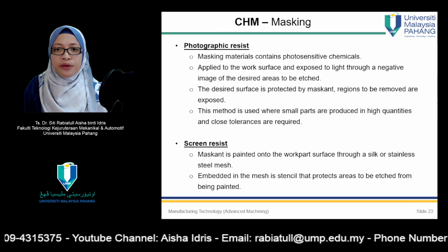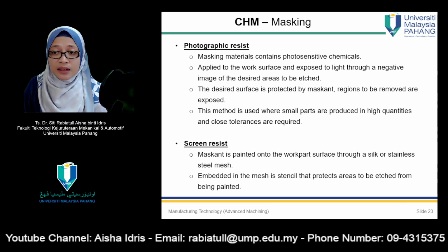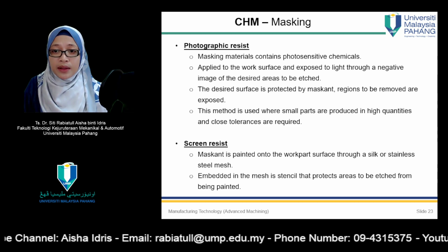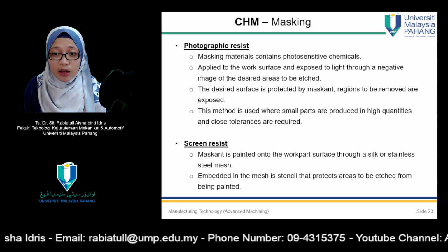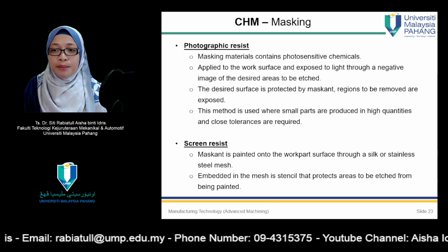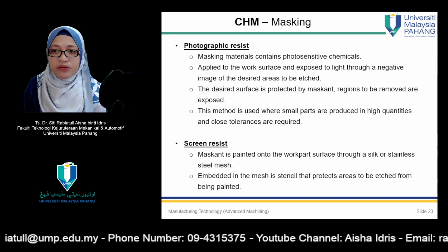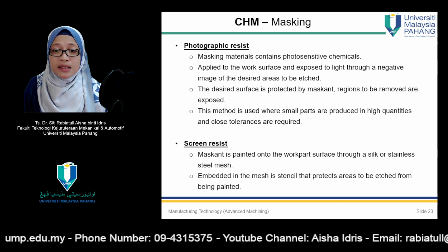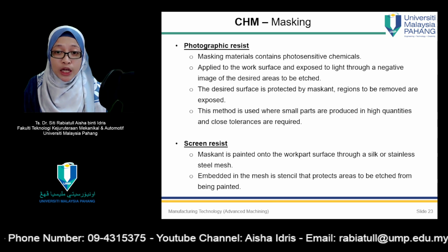The screen resist method applies the masking by means of silk screening methods. In this method, the masking is painted onto the surface through a silk or stainless steel mesh. Embedded in the mesh is a stencil that protects those areas to be etched from being painted. The masking is then painted onto the work areas that are not to be etched.